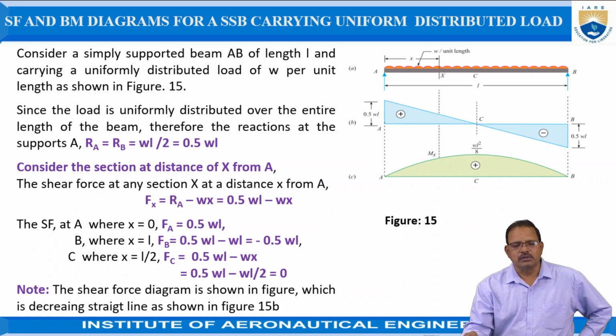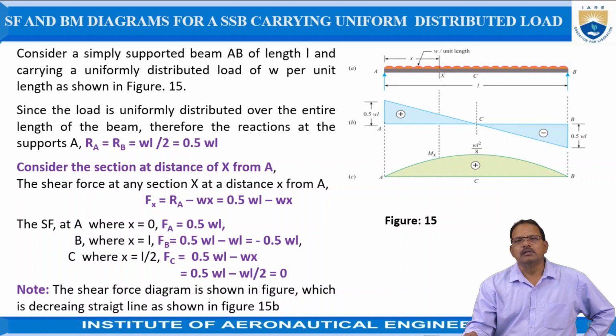any one of these. That is, a combination of point loads and uniformly distributed load, or a combination of uniformly distributed load and gradually varying load, or point load and gradually varying load. For all the problems, since the beam is freely supported at its ends by knife edge supports or ball supports, the moments at points A and B are treated as 0.